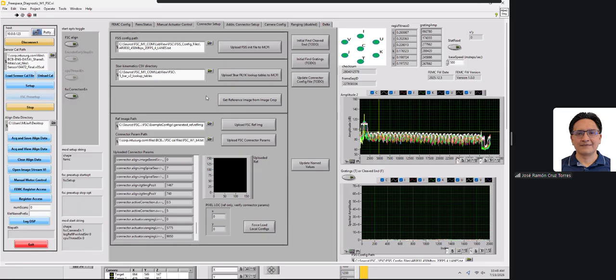So now that we have the right sensor cal file loaded, let's try and see, and we get really good registration fitness, really, really good. You say that it's really good because you need to be as close to one as possible? Yes. So generally, if you're trying to interpret what registration fitness means, anything above like 0.8 is really good. You can make shape with it.